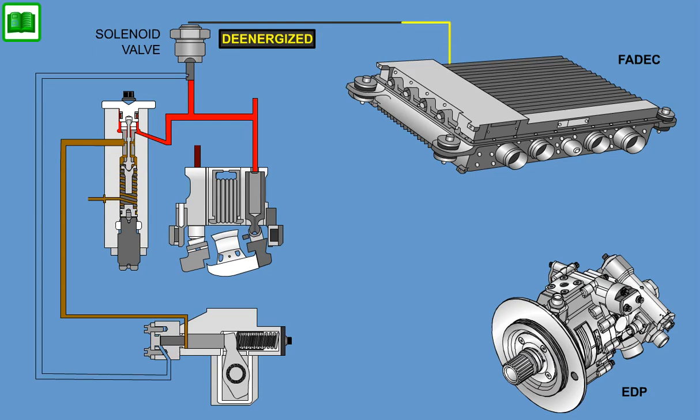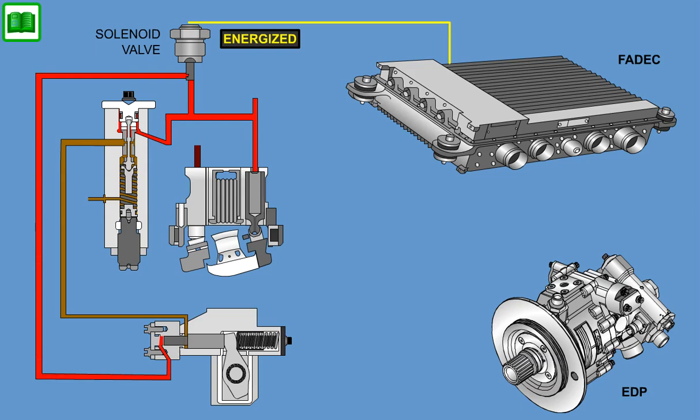When the depressurization valve is energized, the solenoid valve position shifts, resulting in pump discharge pressure being ported directly behind the auxiliary stroking piston, bypassing the compensator. With sufficient pressure applied across the auxiliary stroking piston area, the auxiliary piston pushes on the primary stroking piston, decreasing the hanger angle and reducing the pump outlet flow. Since the compensator is bypassed, the pump discharge pressure is reduced to the minimum pressure required to destroke the unit.